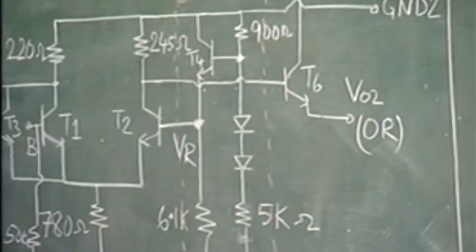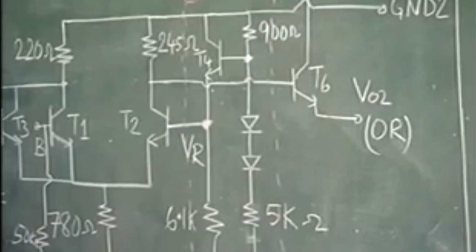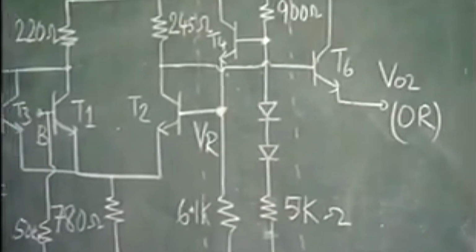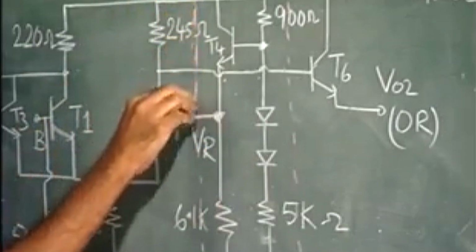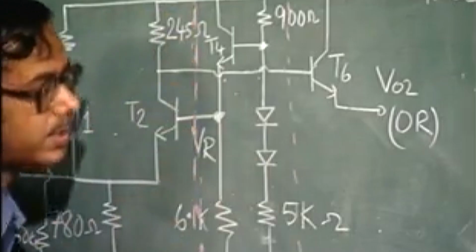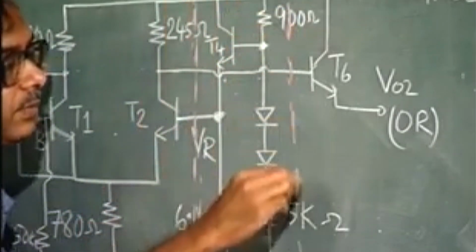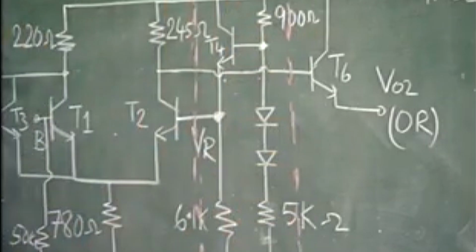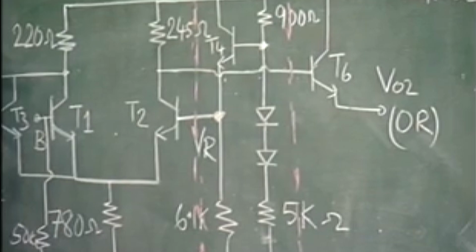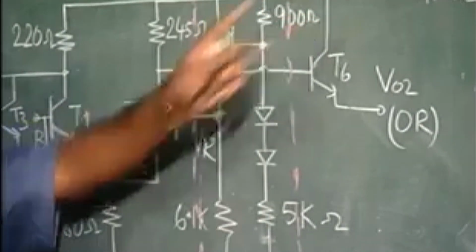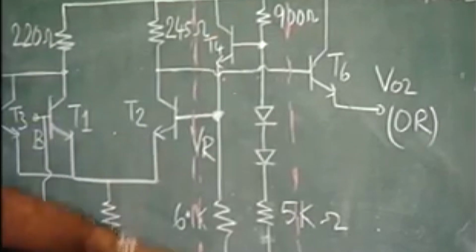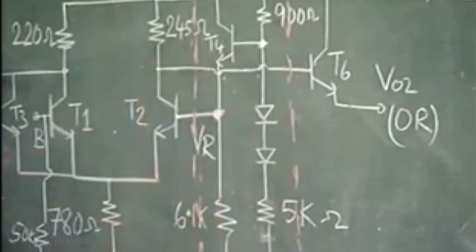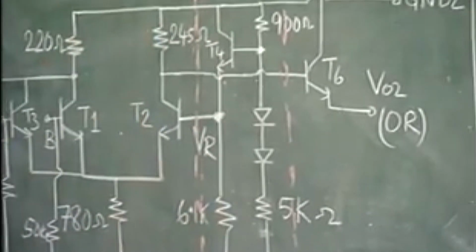You do not have a separate voltage input for reference voltage, but this is generated internally in the chip, from the power supply. So, this part of the circuit generates the reference voltage, and we shall discuss that. The other interesting thing about this circuit is that you have 2 ground connections. Normally you have 2 terminals for the power supply, but here you have 2 ground connections.